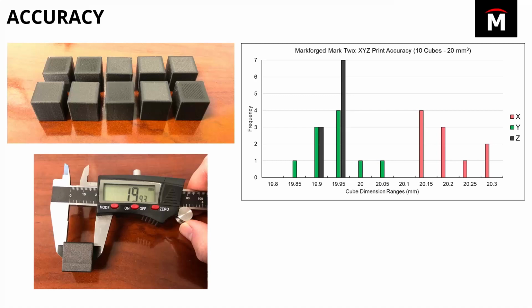And then the Z axis, you can see, is much closer to nominal. And that kind of feeds back to the Z axis being able to print a lot finer resolution, a lot finer accuracy than these other two axes, right? We saw that with that part with the thin 0.5 millimeter grate lines. And you can see that Z axis also is tighter. It doesn't really exceed anything more than like 0.1 millimeters.